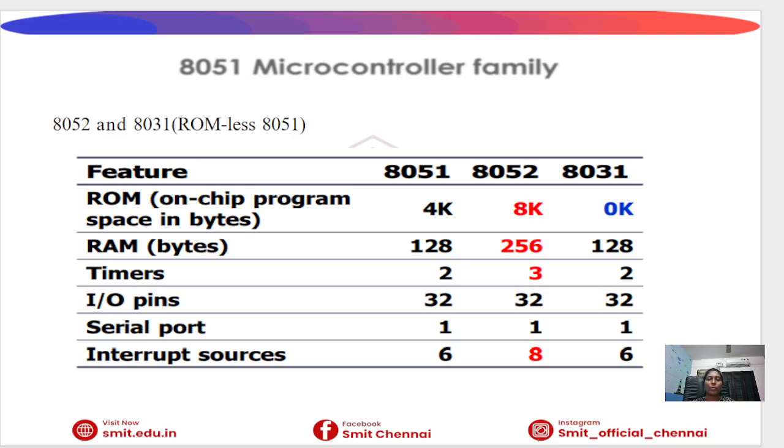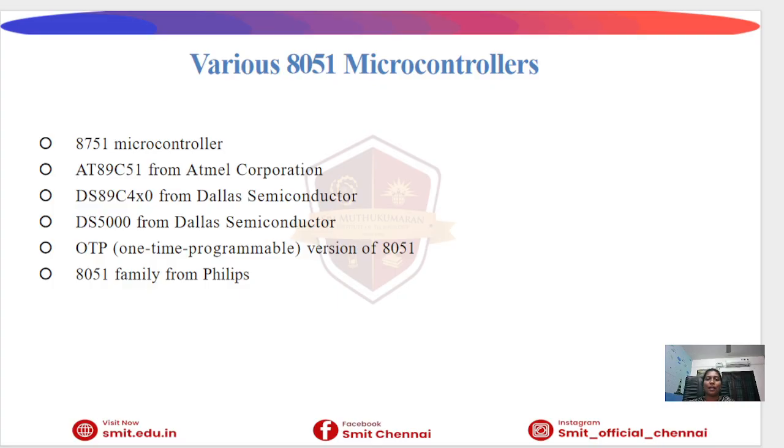Next is the 8051 microcontroller family. Not all 8051 chips are exactly the same. The 8052 is an enhanced version with more RAM and an extra timer. And the 8031 is also called a ROM-less microcontroller. This means the 8031 does not have internal program memory, so we must connect external ROM to store the program. This distinction is very important for understanding later pins like EA and PSEN.